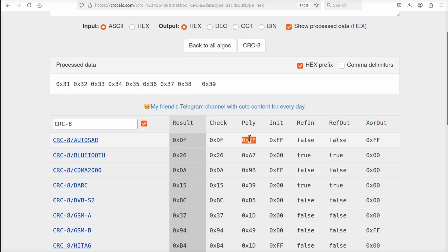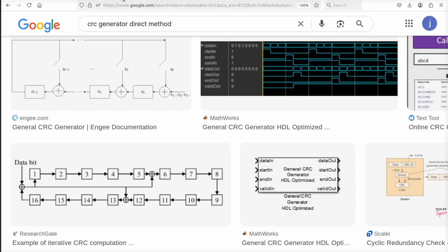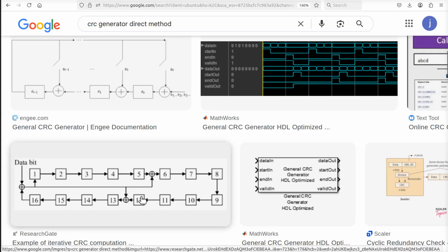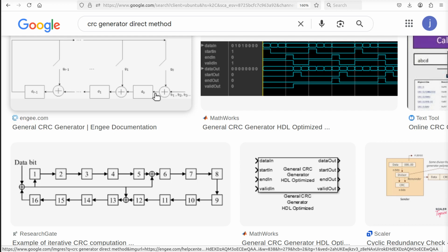All right, the polynomial encoded like this represents, there's a 1 bit in here for each stage in the shift registers where there's supposed to be an XOR gate. All right, so in this case, we've got a 16-bit CRC. Therefore, you have a 16-bit polynomial by definition, okay? And there's always an XOR gate at the first, on the way between the data into the first gate. This will always be here, okay?